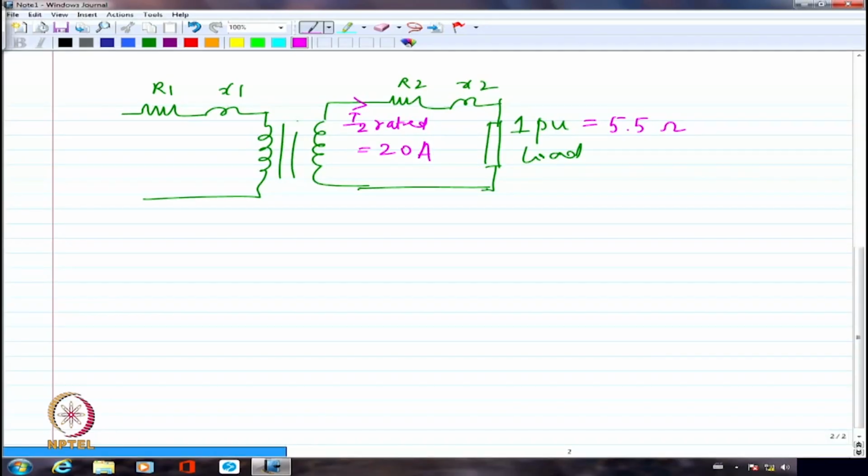So, whether I am looking at both of them from the primary side or both of them from the secondary side, from either side, I would be able to say as long as I am drawing 100% kVA from the transformer, the current that is flowing is 1 per unit. Either I watch it from the primary side or the secondary side. So, there is no question of transforming from one side to another. I don't have to do that at all.